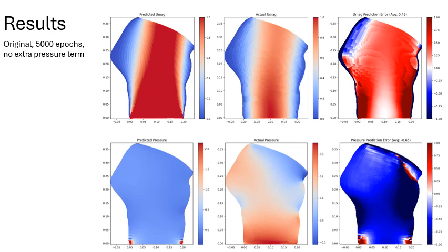We hard-coded a velocity inlet and a pressure outlet. Here, this obviously isn't a fixed velocity. So we're not really sure what they're doing there. It looks like our walls are pretty good, but the error goes up, which means we might have different wall boundary conditions as well. You'll see the predicted pressure field, not much is happening. It's very far off from this, and the error is very large. That's because if we look at the Navier-Stokes equations again, they're driven by a difference in pressure. So when there's no reference pressure, the neural net or whatever doesn't know what to predict.